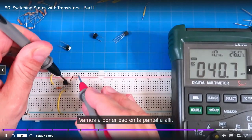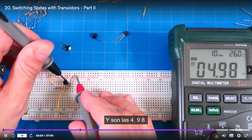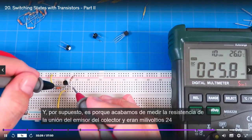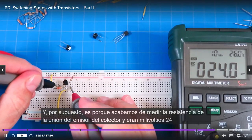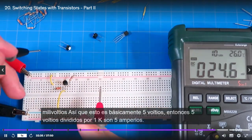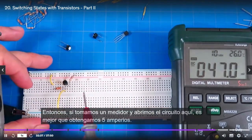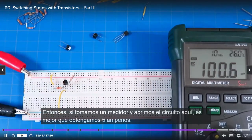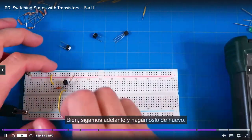Let's get that in the screen there. And it's 4.98. And of course it is because we just measured the collector emitter junction, and it was 24 millivolts. So this thing is basically 5 volts. So 5 volts divided by 1K is 5 milliamps. So if we take a meter and we open the circuit up right here, we better get 5 milliamps. Okay, so let's go ahead and do that.